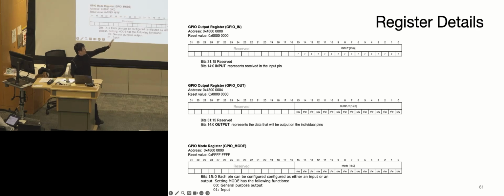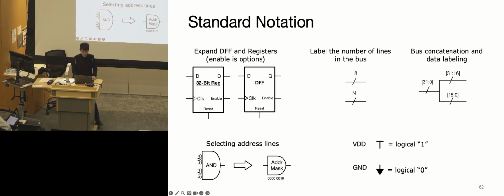This will be quite useful inside of the design questions. Just make sure you know which type of registers the device you're interacting with provides, what their addresses are, and how the bit allocation works. Essentially, which bits are the data you're supposed to write into or read from. And when you draw the diagrams, there are some standard notations. We'll also include that in the datasheet.